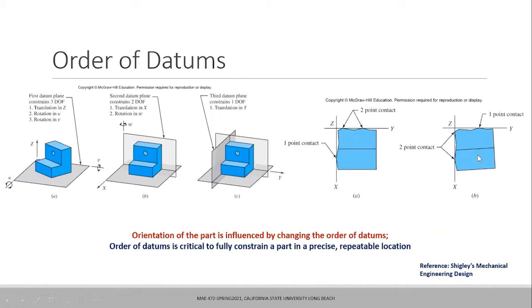And the same part will get disqualified if you are now measuring the distance from the YZ plane and see that it is getting out of tolerances as per the specifications. So depending on how the order of the datums is specified, it is important to mention in the drawing so as to make sure that the part is getting accepted during the inspection procedure.